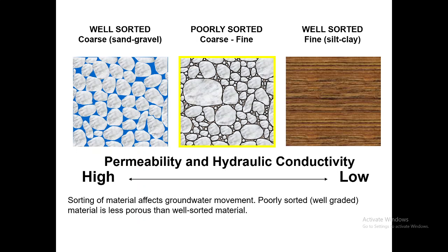And even if we have voids on the top surface, the top layer will normally be covered with water, creating a surface tension on the surface, which will further create an obstacle and hindrance to the flow of water from the top to the bottom. That's why it is the least permeable structure allowing the water to move. So the permeability and hydraulic conductivity increase on this side, where we are having open voids for the water.